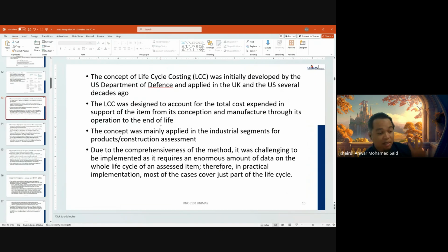If we combine these individual profiles within the concentration intervals, we get a single continuous stepping line representing the system total absorption capacity, which is what we call a limiting composite curve. After this, we'll have an example.